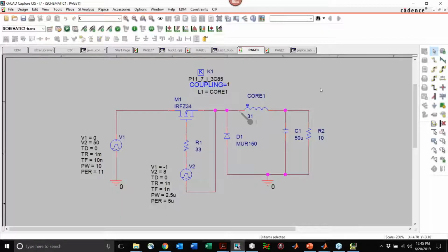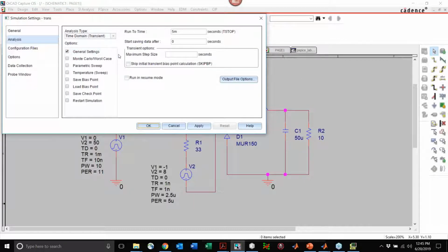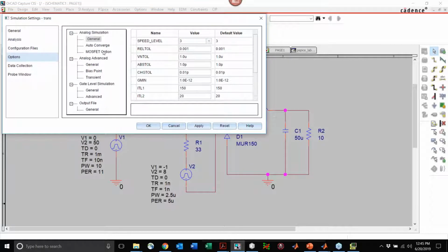Yes, so in our PSpice tool, we can use an Autoconvergence tool, and I mentioned this a little bit in our slides, and it's good that we bring it up again. When you set your options, you can turn on the Autoconvergence option here in PSpice. What you'll do here is specify how much to loosen your tolerances so that you're able to simulate. And as I mentioned, the absolute tolerance for the current here, that's the one that often causes your power supply circuits to not be able to simulate.